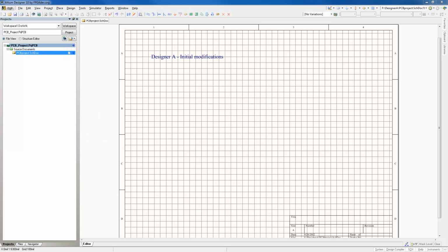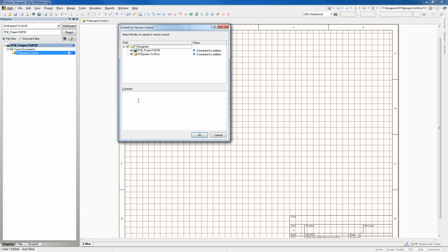Okay. And what's going to come up is this here, and then you're going to get a comment. Now I really recommend the use of the comment. You don't have to put a name, and you don't have to put a date, because that information will already be captured within the version control. If you go to the repo browser, or if you use the storage manager in Altium Designer, it will give you that information. But this comment is really important, because if there's many changes that are made, or changes that are being made by your colleagues, this can help you decide which is correct, especially if you get in a situation where two people have gone off and now you need to merge.